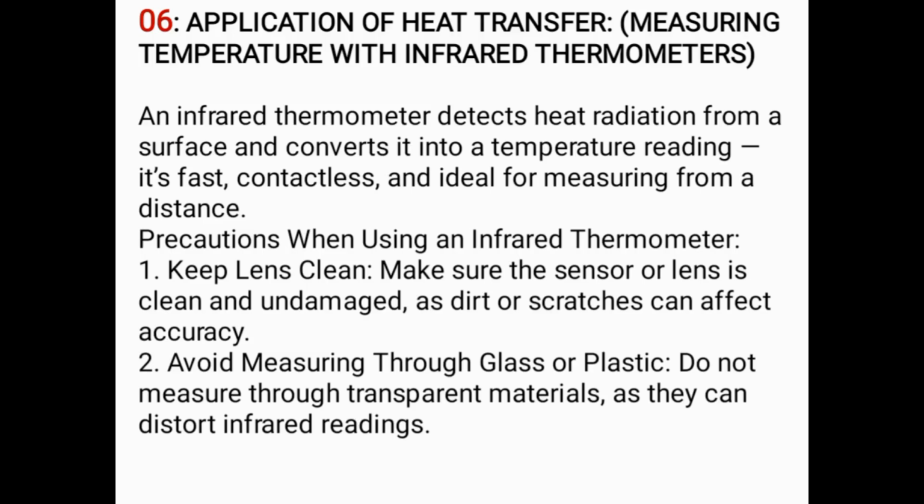Precautions when using an infrared thermometer. 1. Keep the lens clean. Make sure the sensor or lens is clean and undamaged, as dirt or scratches can affect accuracy. 2. Avoid measuring through glass or plastic. Do not measure through transparent materials, as they can distort infrared readings.